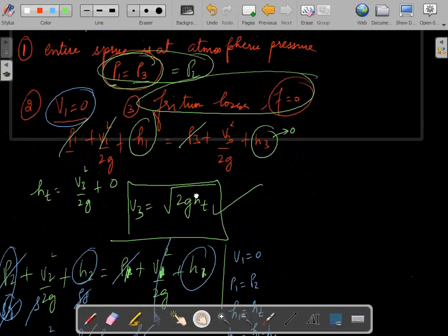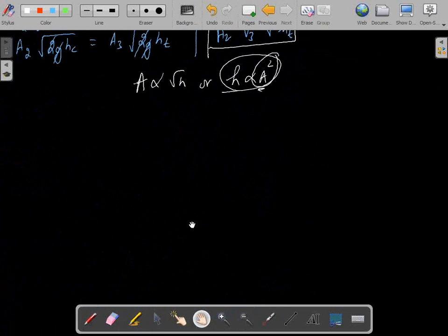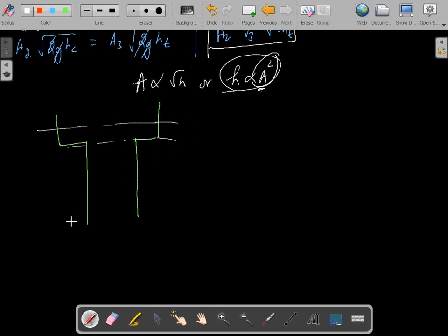Now, if you create a cylindrical sprue, I leave it up to you. Draw these three sections, and perform the same analysis that we did. Now you will come to a conclusion that when you have a straight profile of the sprue, there will be some flow disruptions.